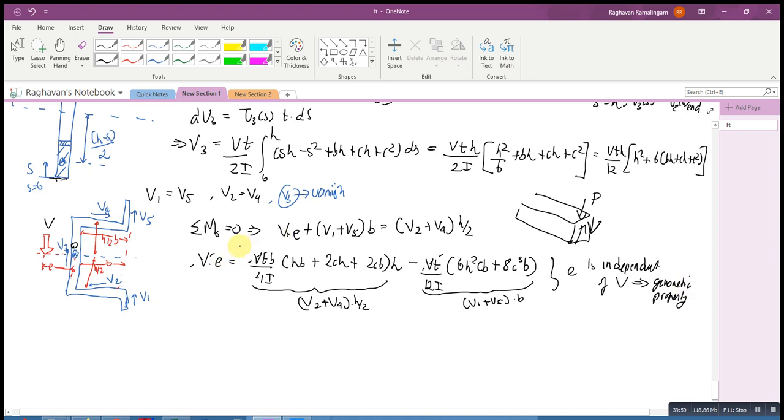And so E, the shear center distance, equals, it's now just a job of big simplification. I'll write the final expression. It's not strictly speaking very simple, but I have collected as many terms as I can. H plus b minus c plus b into 3bh square minus 8c cube. So this is the expression for the shear center.